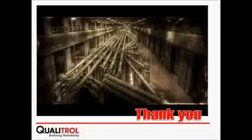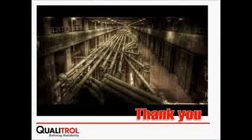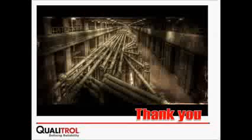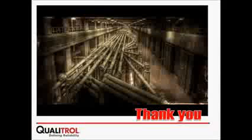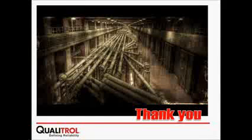The next question, Carlos, was how UHF couplers are installed on power transformers, and we had a similar question earlier. The answer is, if it's an existing transformer, then the options are limited, but you can put one on the drain valve. We have a drain valve sensor that works without draining the oil from the transformer. It could be on a hatch.